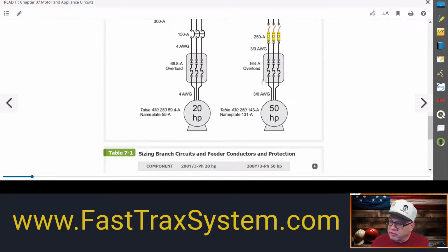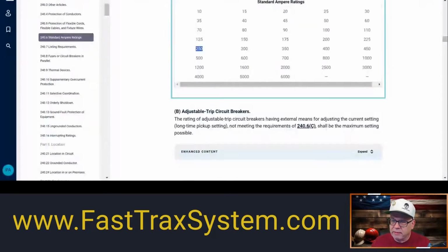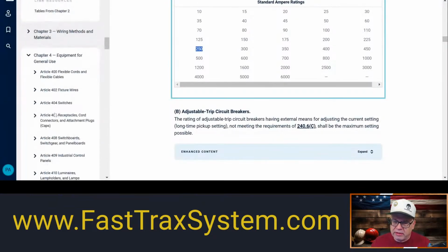As far as the conductors, same concept as before. We're doing them at 125%. That's in accordance with 430.22, because we're just doing this single motor here. In that case, it's the FLC, so 143 times 1.25 gives me 178.75, so we'll say 179 amps. Obviously, we're going to be in the 75-degree column. So let's go to the NEC, and we'll go to 310.16.